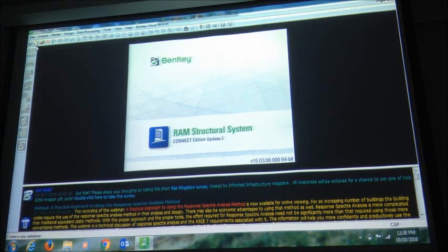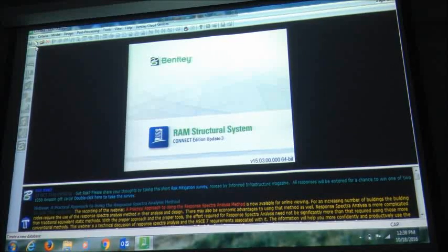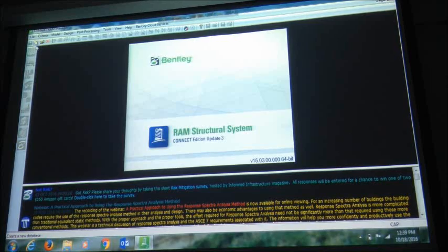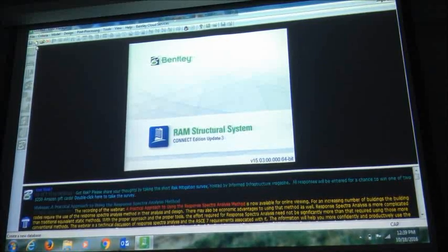I know Revit, CAD, MicroStation. These are where you can make a DXF file. You can import the files as a DXF file, either 3D, 2D, floor plans, whatever. Again, I'm saying it in terms of Revit because that's what we use all the time. We bring the Revit file, analyze and design it, and send it back as a Revit file also. So you can do that.